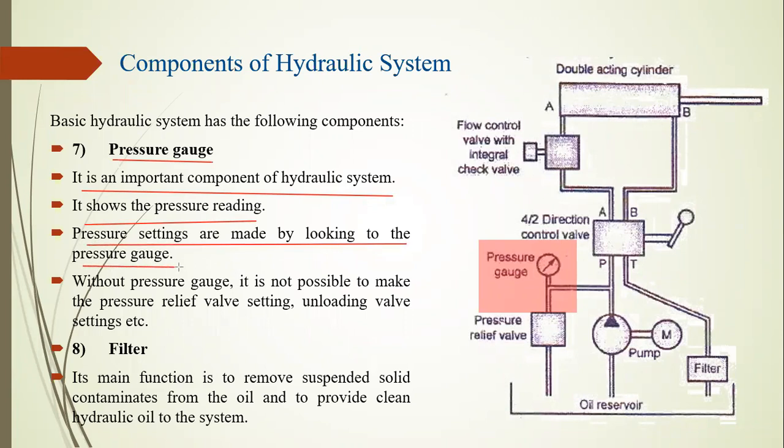All hydraulic systems, all pressurized systems, require a pressure gauge. The pressure gauge is the most essential part in a pressurized system, because high pressure works inside the system. High pressure means 10 or 20 times higher than atmospheric pressure in our hydraulic system. So it is necessary to know how much pressure is running inside the system. It is an essential part of any pressurized system.